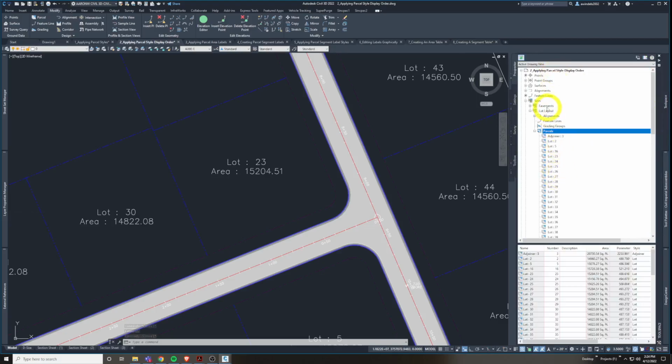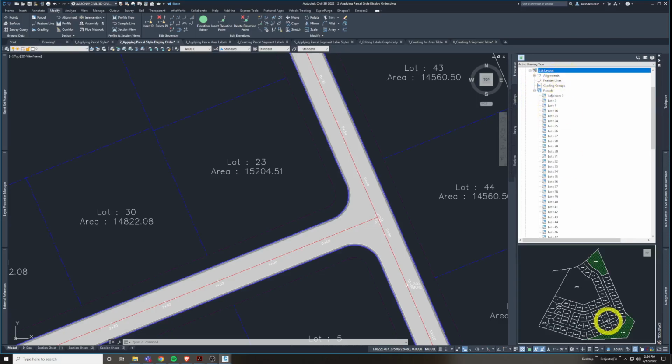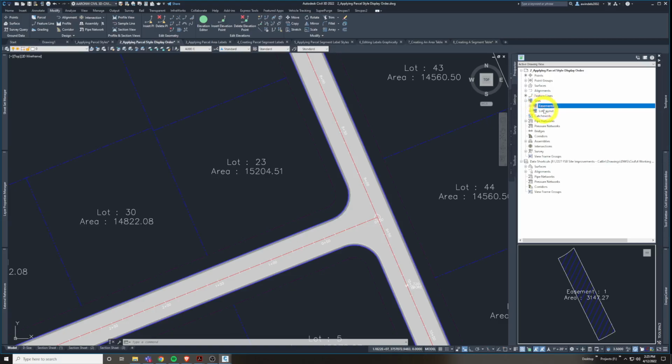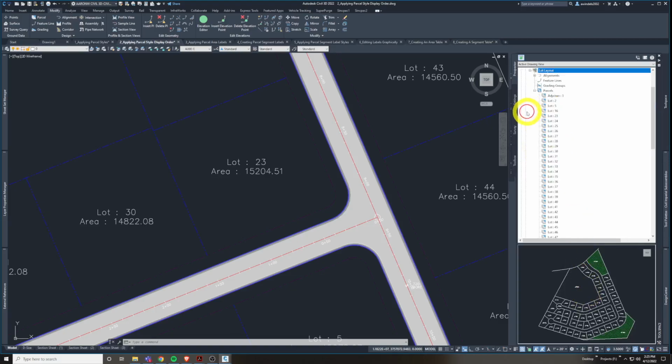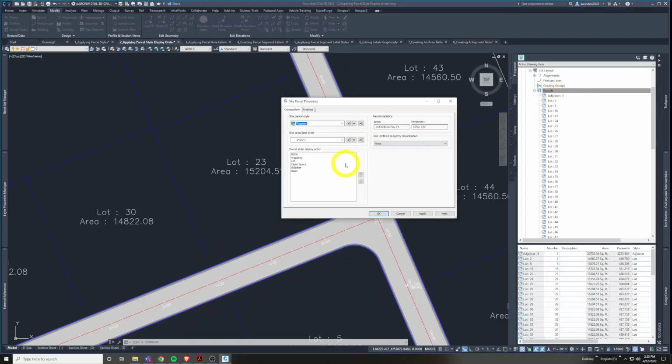Let's go to all of, we're in our sites, lot layout, not the easements. This gives us a preview of all the sites, right? Easements, just the one. And let's go back to the header and say properties of all parcels. We're going to change it to this order right away, then adjoiner, and then it wants us to change it to open space, then lot, then property, then basic. Basic is like a standard style.